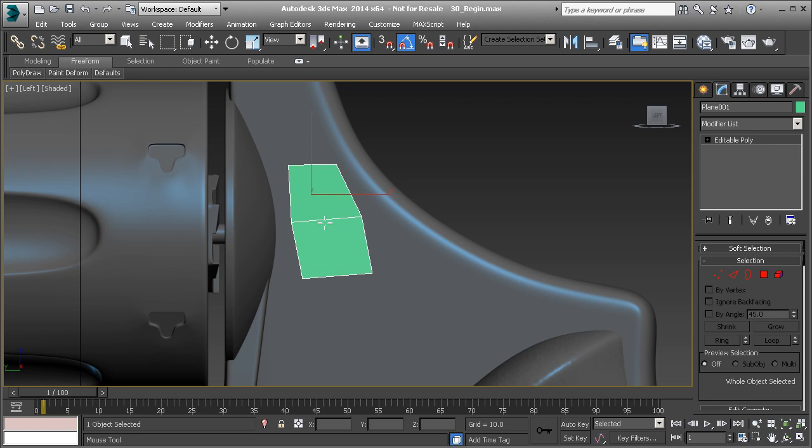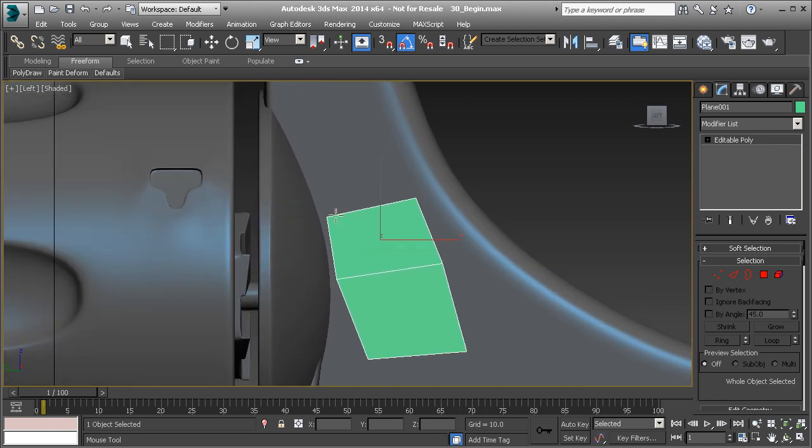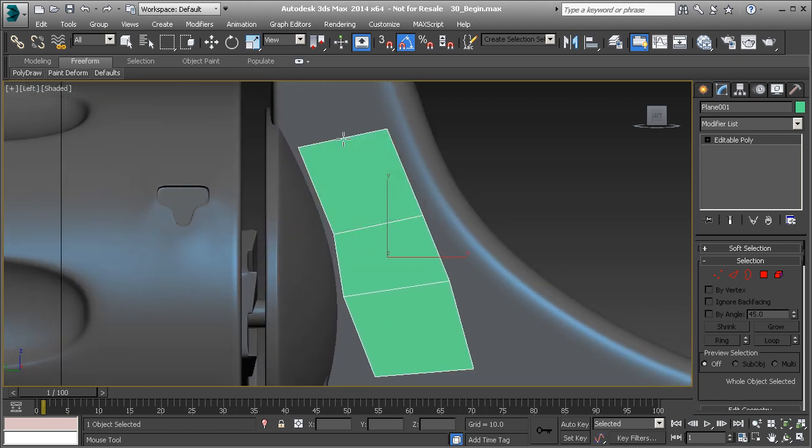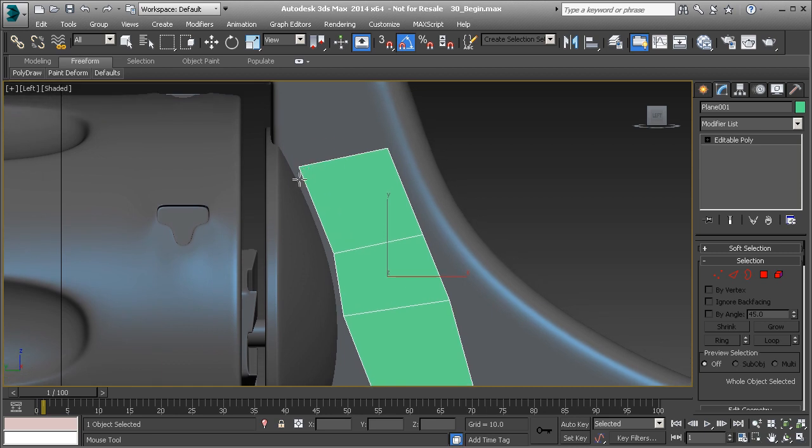And then what I'm going to do is hold down Control, Shift, and Alt, and that will allow me to move the individual vertices of that. So this allows me to quickly work. All right, so let's go ahead and get started. Let's hold Shift. I'm going to drag this up here. Let's hold Control, Shift, Alt, and let's move these points.